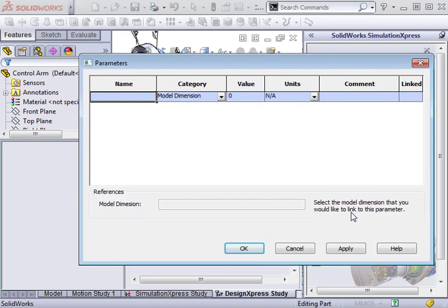I'm looking for. One limitation to optimization using SimulationXpress is that you can only optimize one dimension at a time, based on the part's strength in a static loading test. Full versions of simulation have virtually unlimited possibilities for optimization that can explore vibration or buckling responses at the same time as strength across many dimensional variables, since the optimal design is often a compromise between two or more features. It's up to you as a designer to choose a dimension that could improve the design of the part.